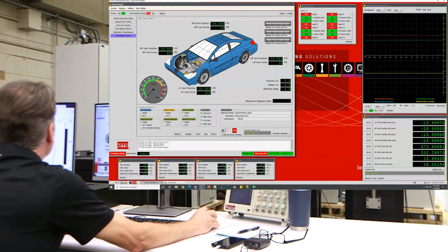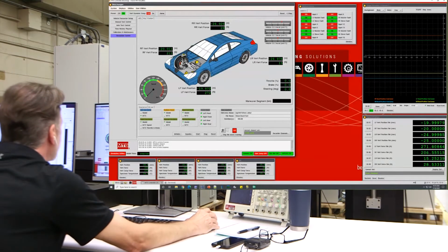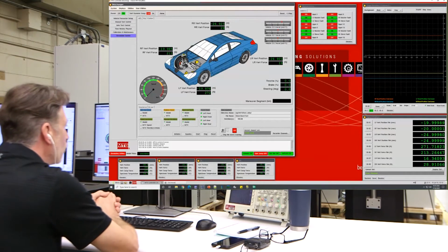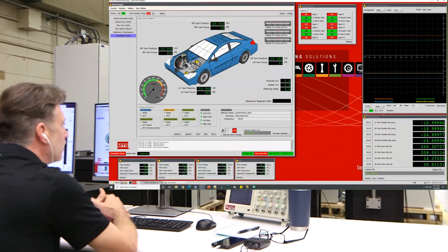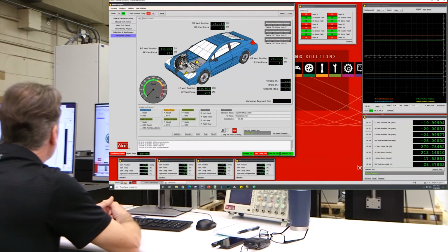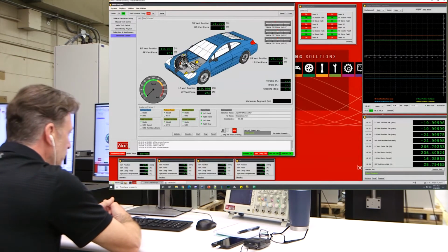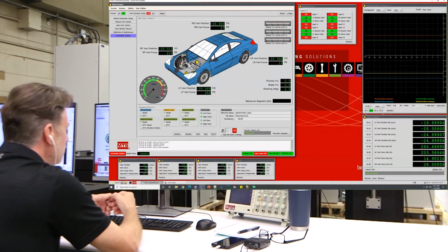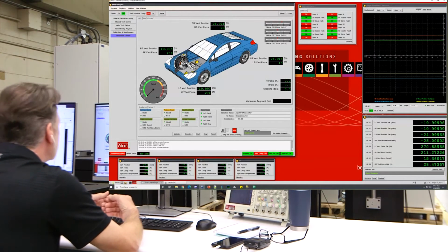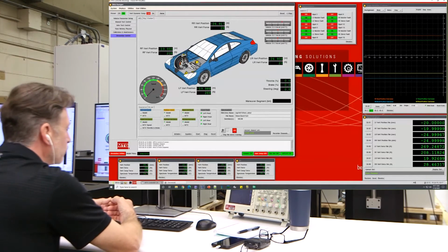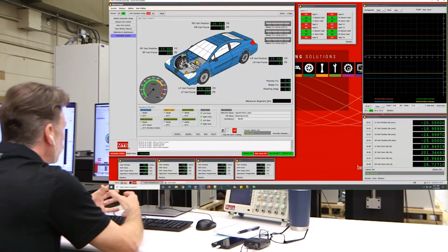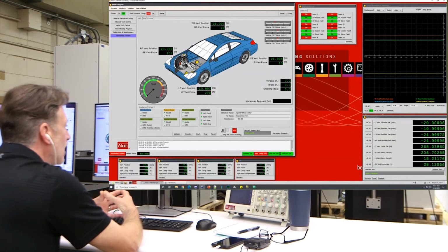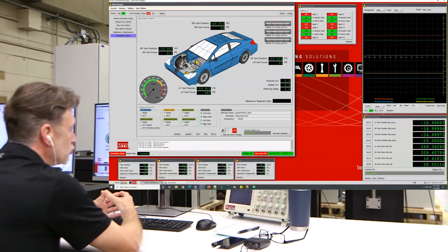One other primary tab that I want to go over is the simulation tab. This is essentially a manual control tab for the mHIL, for the simulation. Juan went over the adaptation that takes place that's required to put the dampers physically in the loop with the rig. There's another adaptation that we do. There's actually two aspects of it. There's the modifications to the model to take an external input and use that in replace of internal calculations or maybe a table. But also we put a wrapper around that model. This allows us to coordinate or supervise the process of putting the simulation in closed loop with the rig.